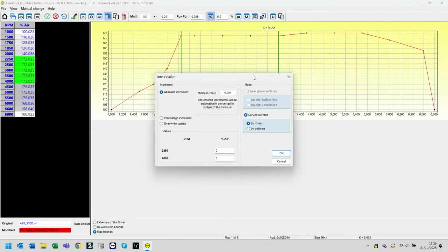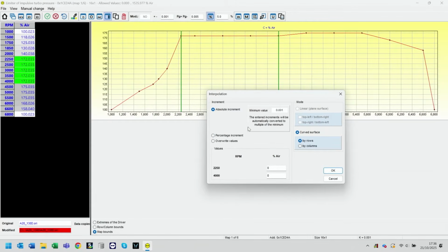of the ECU. So we're going to make some changes now with the right click function, and we're going to want to scale our modifications up. So we want to take our peak and have it at 4,000 RPM. That's where our peak torque is. That's where the best of the best on the engine is going to be produced. That's where we want our peak boost to be.